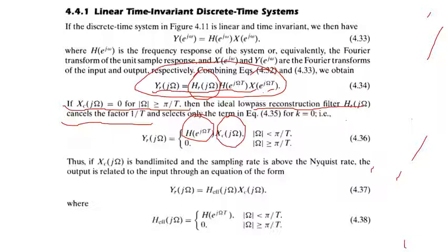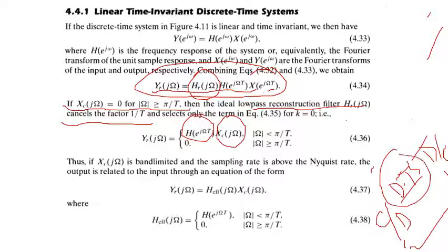So we are not worrying about C to D, the discrete time system, or the D to C. All this boils down to the discrete time system and the Fourier transform of the input. The output will be equal to the original spectrum multiplied by the response of the discrete time system in this limit, because beyond this limit the output will be 0.